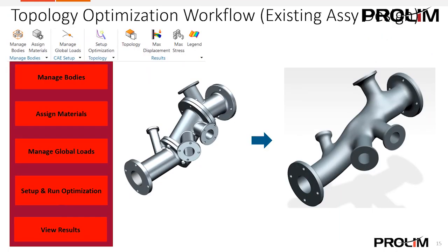Now let's look at an existing assembly design. We're going to take this existing assembly and optimize it into one individual part. On the left you see we have a design that has several components. It may have several setups in there, including some weldments, and time to assemble it together. So just by optimizing it, we eliminate a lot of those extra steps that are not needed. We're also able to make our inventory smaller just by having one component versus several components.